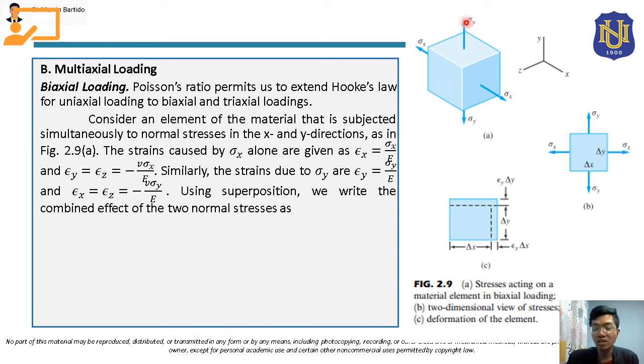Due to this stress in the y direction, the element will also experience strain in the y direction, and the strain in the y direction will be equal to sigma y over E. Also, due to this normal stress in the y direction, the element will be subjected to strains in other directions: in the x direction and in the z direction.